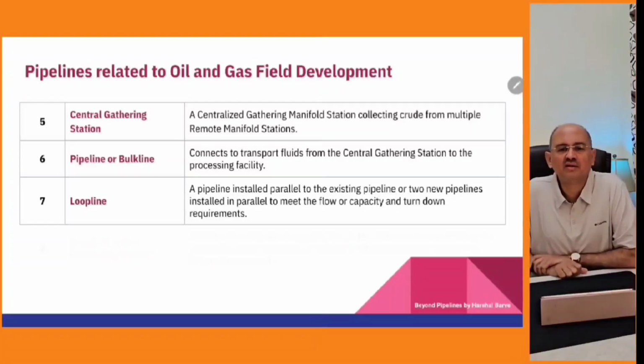If the line is flowing sufficiently full, then the corrosion initiation doesn't take place in the pipeline. They are normally carbon steel pipelines which need to be regularly pigged and maintained, and chemical inhibition is done to maintain the design life and extend the life further. So when the line is not flowing full and is running with very low velocity, then separation of liquid is going to happen, temperature drop is going to take place, and because of that, stagnant water can get deposited at the low points in the pipeline, which can initiate the corrosion reaction.